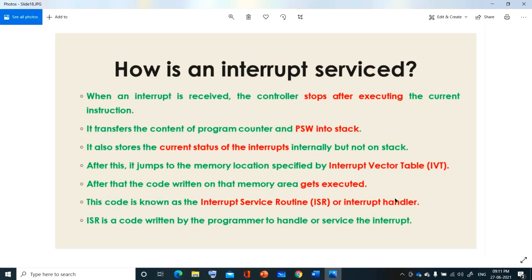Let's say once I start the counter, I want to check whether the interrupt flag is set or not. I need to check every time whether the counter has reached the maximum value. Once it reaches the maximum value, the interrupt flag occurs and will be set. Then your program has to stop. To stop the program, it has written the corresponding vector table and vector address.